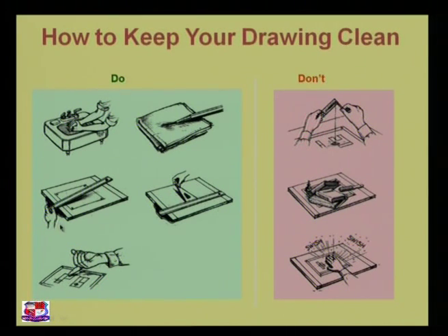Sometimes the T portion of the T-square may be broken if you hang it like this. If you want to draw some angles, then rest your set square on the drawing sheet. Do not hang the set square also. If you hang the set square, then you might get wrong angles.